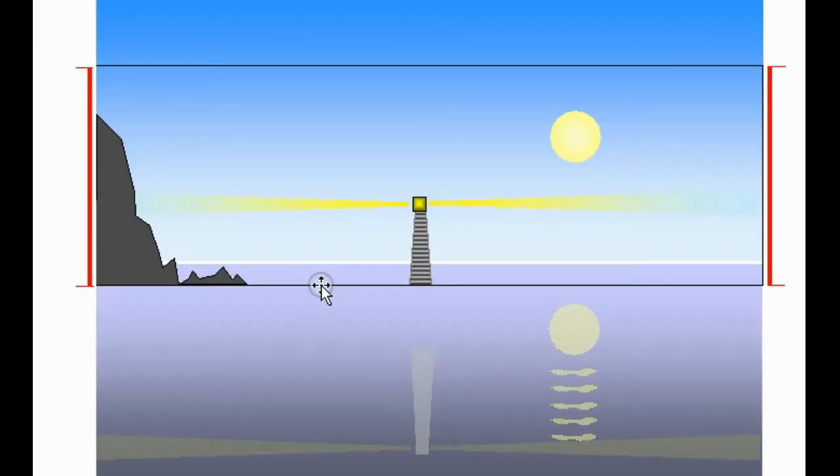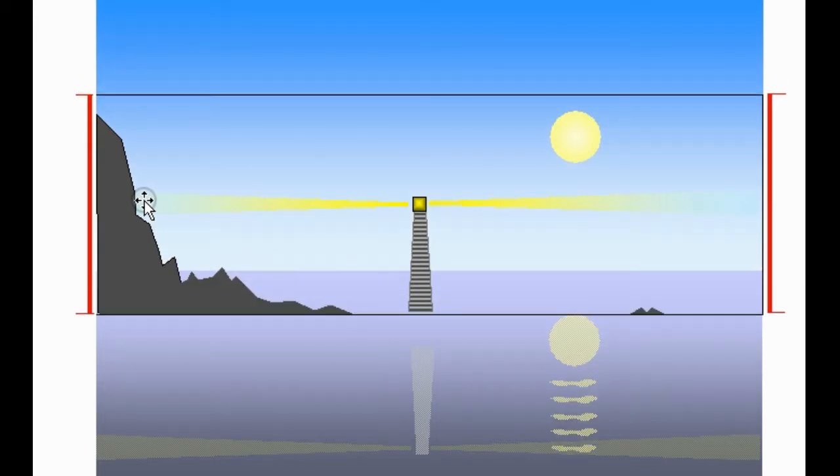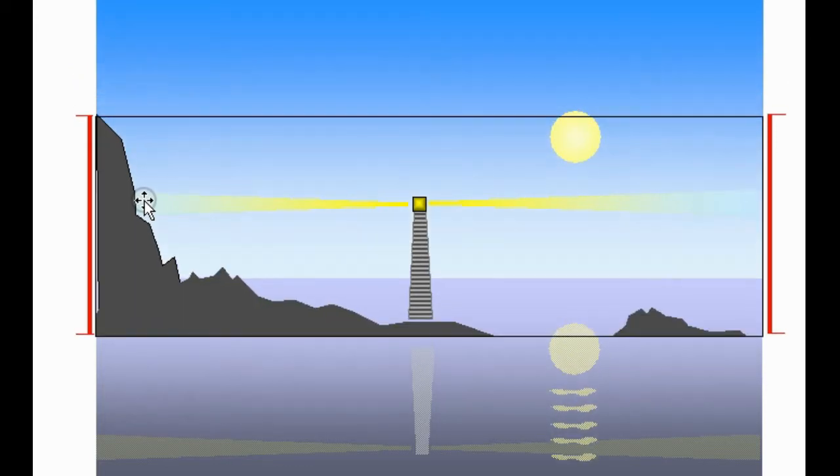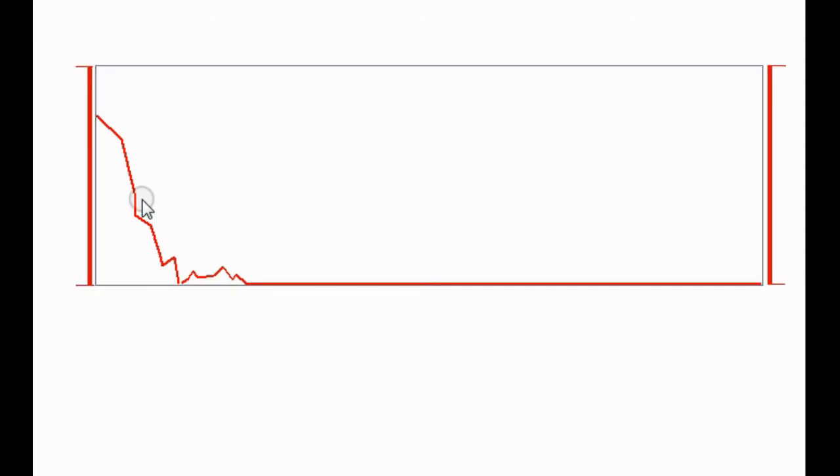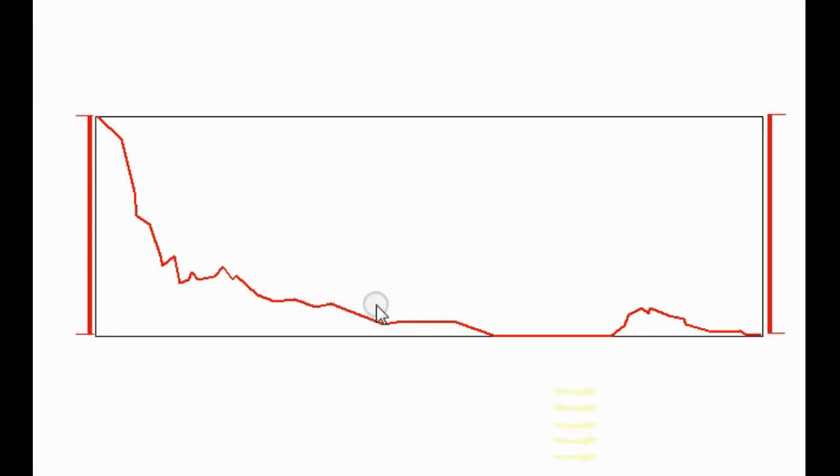Going back to our ocean view, we can now reduce the level of water. This is the same as reducing the amount of attenuation. It makes our analyzer more sensitive. If we look at the spectrum now, it would look like this, whereas before, with maximum attenuation, we saw this, where much of the lower level signal was lost to view.